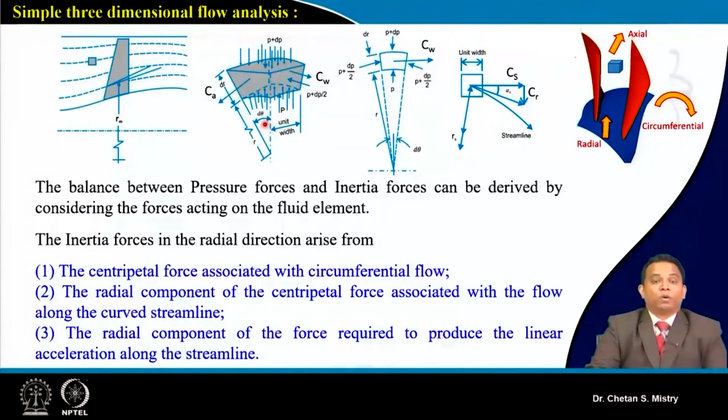Now we know because of the movement of this particle within the blade passage, we will have a rise of pressure, that is my diffusive action. So you can say I will represent my pressure on the downside as P, and on the upper side I will put my pressure as P plus dP.